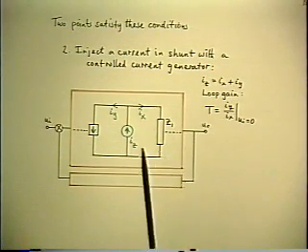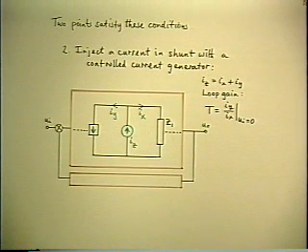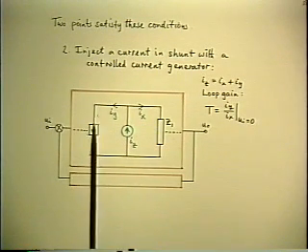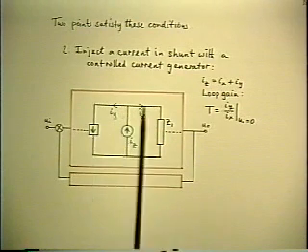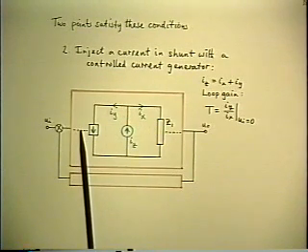So you can measure loop gain by voltage injection or by current injection, but you have to choose the right one. At any arbitrary point, you can't just choose whichever one you feel like. Only one of them can give you the right answer at a particular point, and maybe neither one of them, if you can't find either of these generators. But certainly they're mutually exclusive. You can't have both of them give you the right answer, because they require opposite extremes of condition to be valid.